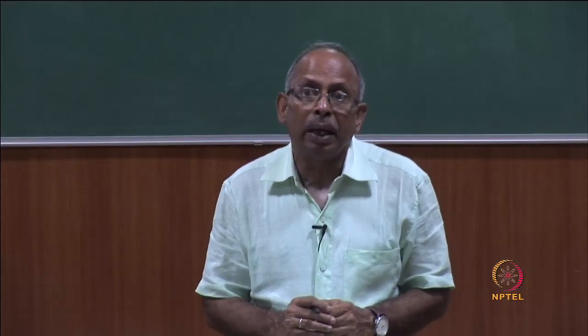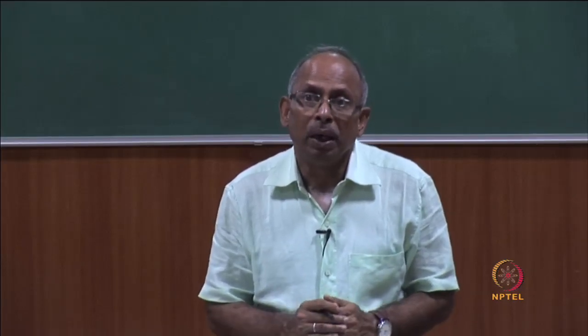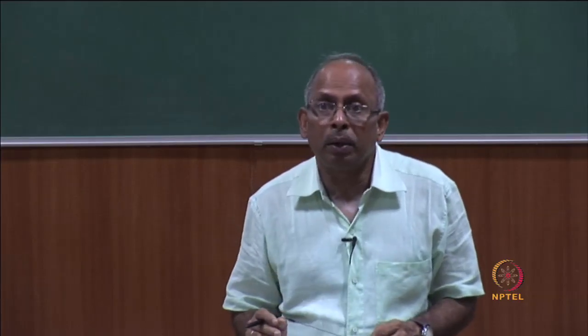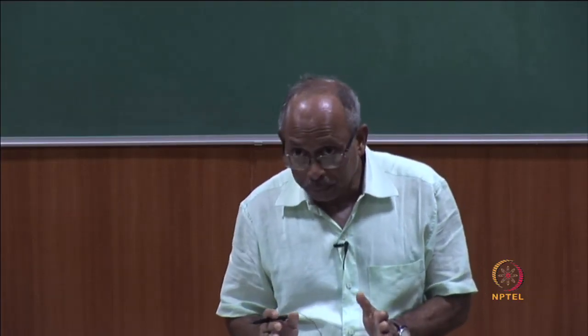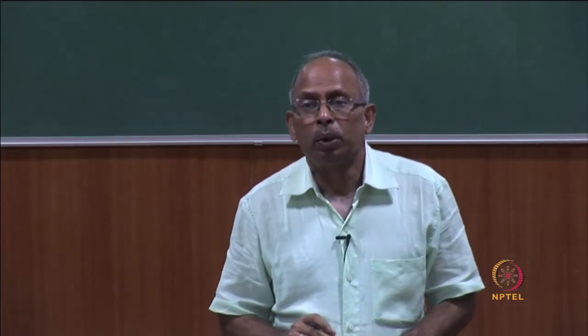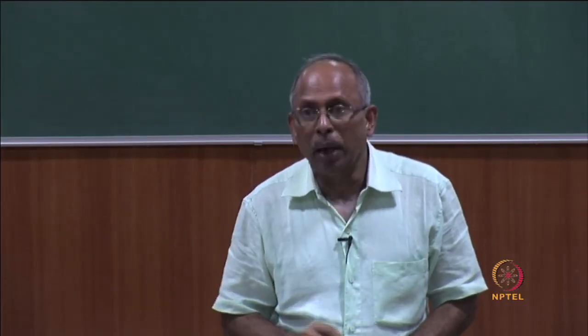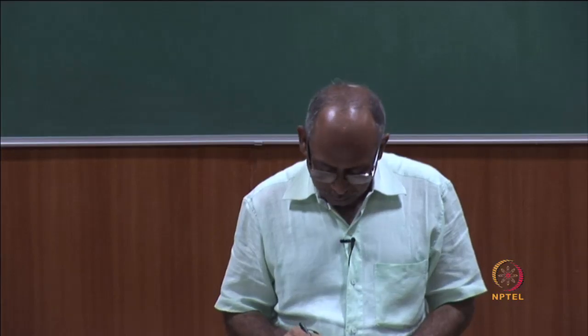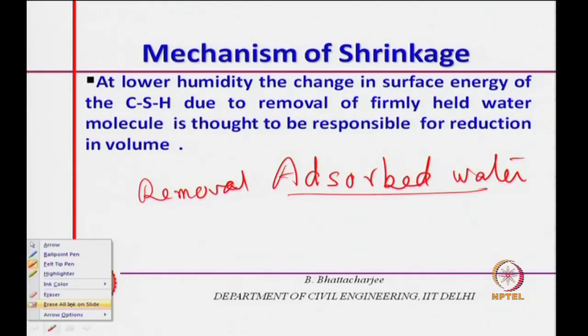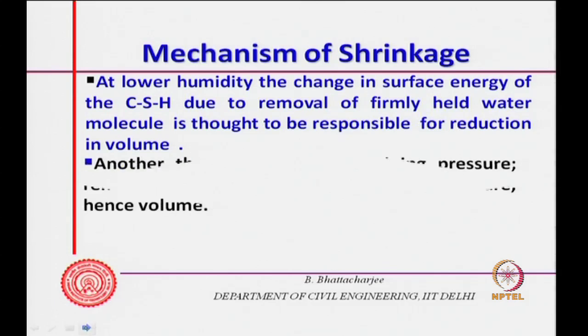This results in forces causing a kind of pull within the material, and therefore reduction in volume. So, this is another reason, a collapse mechanism sort of. Adsorbed water removal can cause change in the volume or shrinkage.